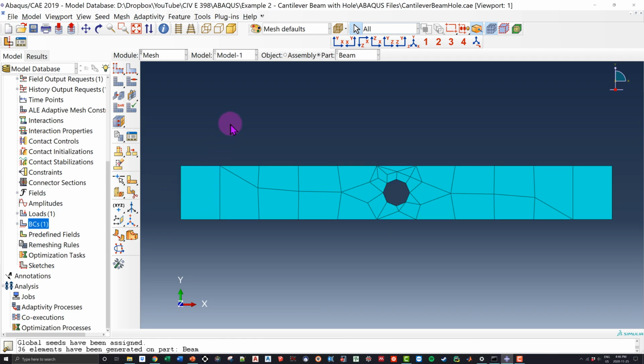So one of the key things that we're going to have to keep in mind when we're doing these mesh calculations is we want a thinner mesh in order to obtain better accuracy. So right now, I just went with the default mesh that ABAQUS gave me. I'm looking at this and saying, you know what, this is a little bit big over here.